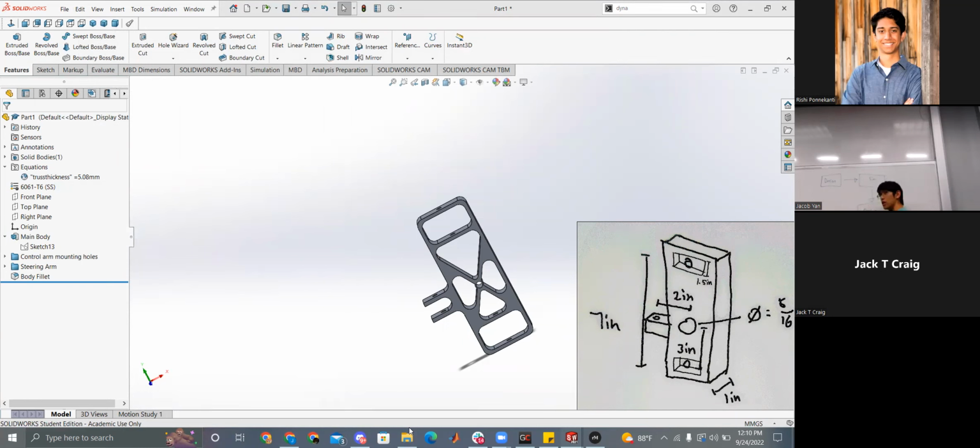So you take that simulation data, you take those mass properties, your buckling simulation data, your stress simulation data, and you see what areas need to be reinforced, what needs to be changed. You talk to other people, they might give you some other ideas. Evaluate, and then from there, you go back to design, and you change your design. You make the change you need to make. You make your design better, and then you keep going in this loop.